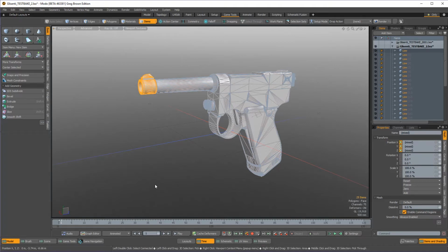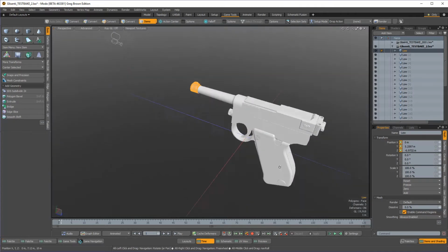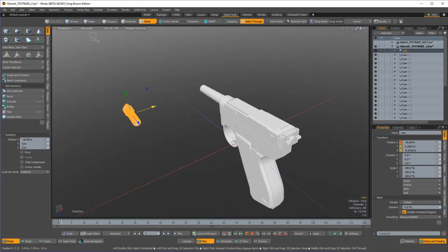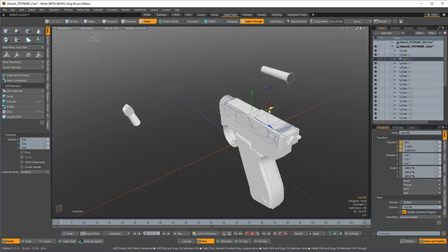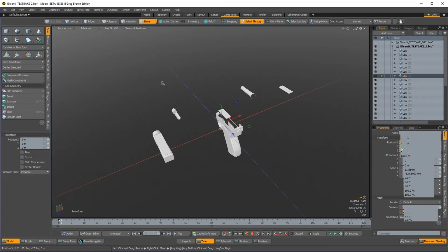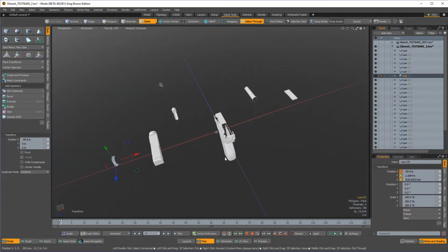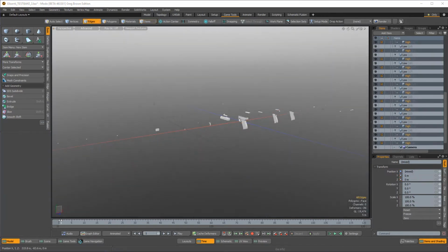And if I go ahead and advance the time by 1 frame, I can start moving my meshes off place and setting up a basic exploded bake. Now, this could be achieved with some sort of scripting to make this go a lot faster. But in this case, there aren't too many items, so you can do it manually. However you want to, just make sure your items are spread out enough so that you don't get overlaps in your bake itself.